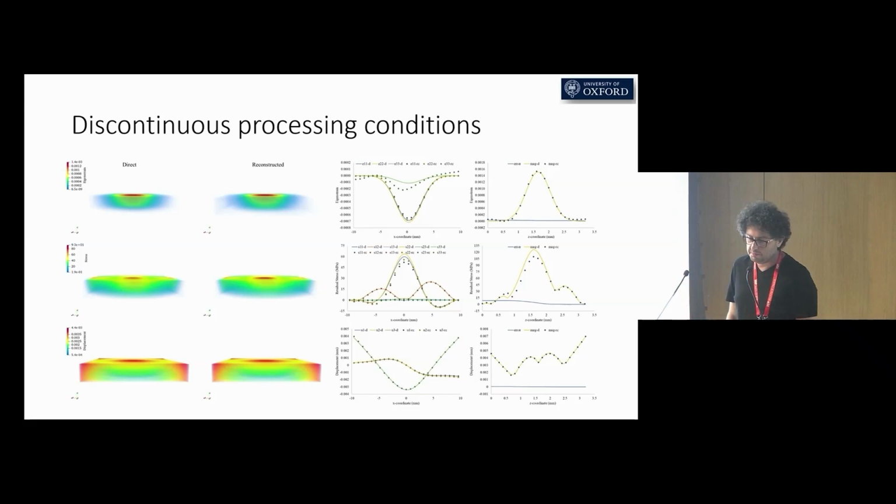Same experimentation and quantifications were applied. Again, we obtained very accurate reconstruction of all components of residual stresses, but we had some slight deviations in some components of eigenstrain. It doesn't matter in this case because visually we don't see any difference, and reconstruction of stresses is very accurate.